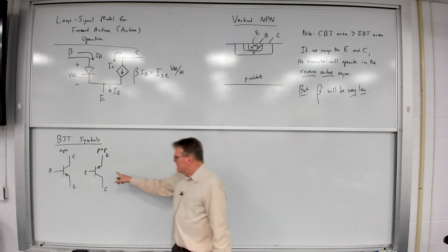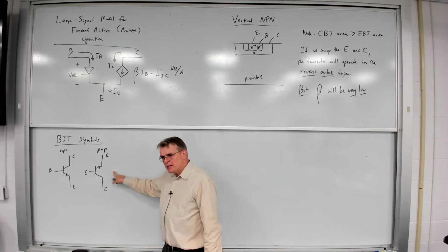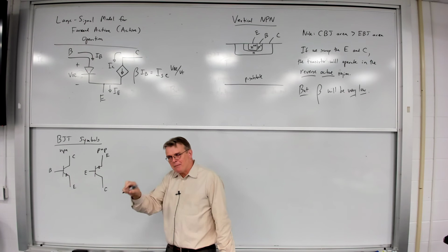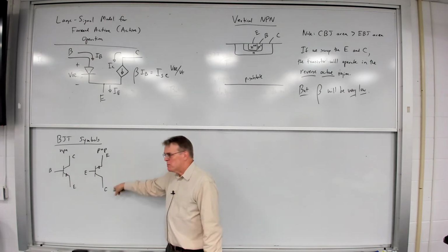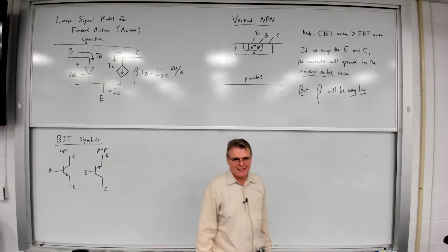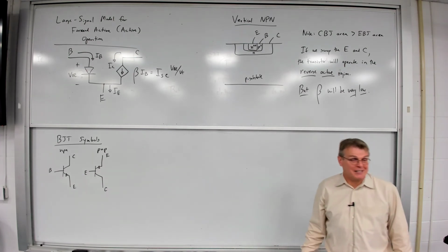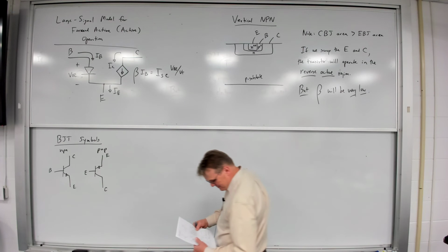Once again, I think you have to be careful because I think when you pull out a generic PNP model in LTspice and drop it into your circuit, I think it always puts the emitter on the bottom. So you've got to be careful about that. You'll quickly find that your circuit isn't working because you've got to flip the transistor upside down. Okay?